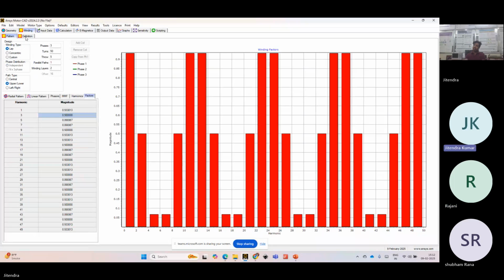See, when you are winding any machine, distributed winding has lower harmonic content than concentrated winding. What does distribution mean? It means you are distributing conductors sinusoidally along the periphery of the pole, or in the slots. By distribution, you are not loading any single tooth.